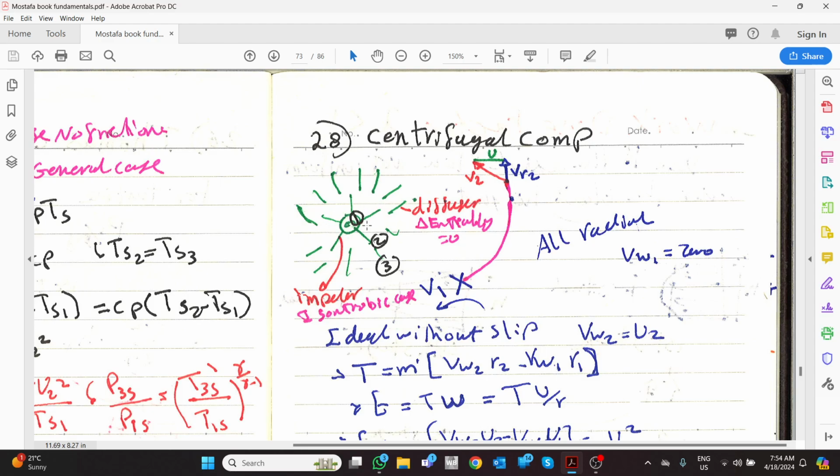So the work done on the compressor is at the runner itself, and whatever is happening in the diffuser area is assuming a constant, no change in the enthalpy, which means no power or work has been generated or given to the air here. We are assuming that whatever work is injected inside the compressor at the runner is an isentropic process. This is the ideal case, and then we're going to check, if it is not isentropic, which is the actual case, how we are going to manipulate it.